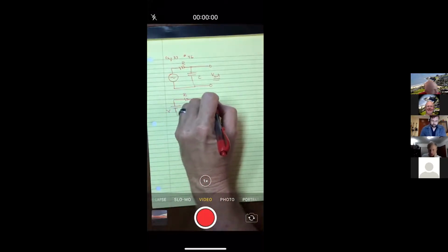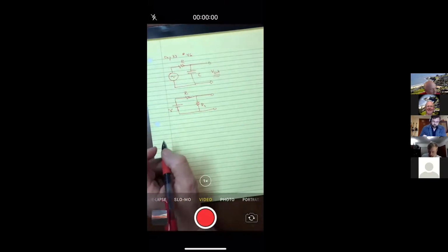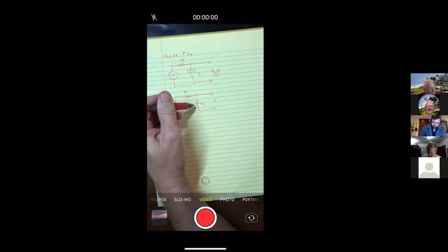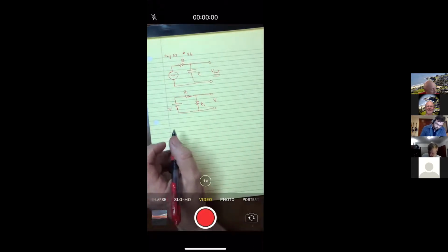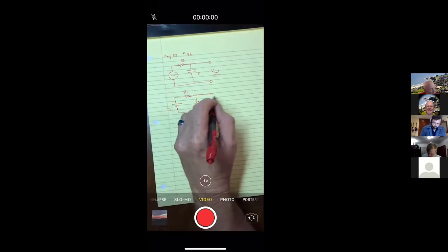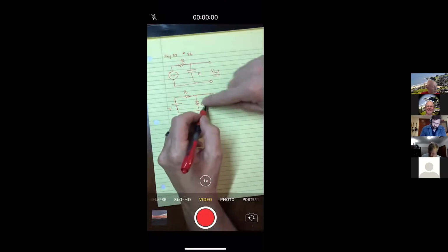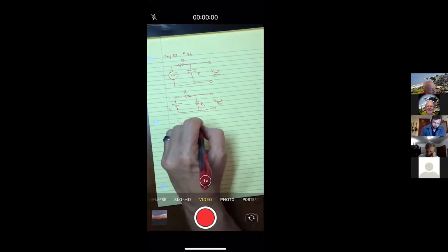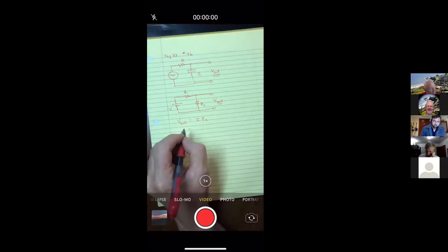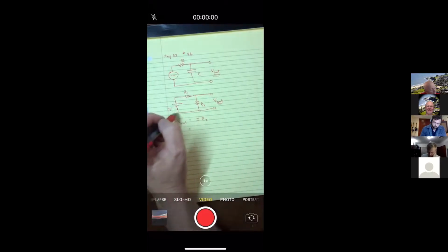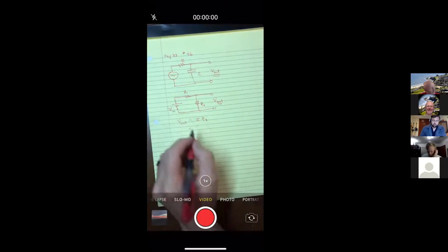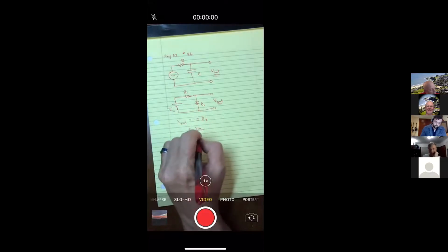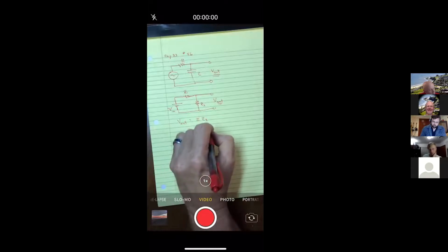And the reason we like this phrase, voltage divider, is if you measure the voltage across this element, which in mine is resistor number 2, and I'm going to direct that back to the capacitor in a second. The voltage across number 2, which is what I'm measuring, so the voltage out, would be the current times resistor number 2. Well, how would you get the current? The current would be the voltage you're putting in, voltage in, divided by, and the current would just flow around, these two would be in series, so R1 plus R2, times R2.